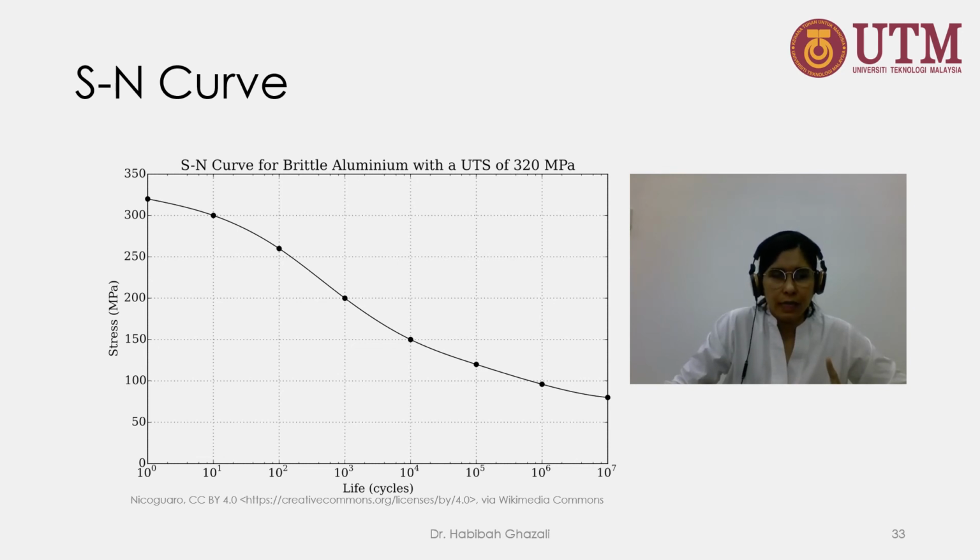They found out that at the force that will generate the 320 megapascal, they only need one cycle and this material is going to fail. And when they performed the test that will generate 300 megapascal stress, it will break after 10 cycles and so on. They performed another test with the cyclic load that will cause about 260 megapascal stress. It's going to fail after 100 cycles.